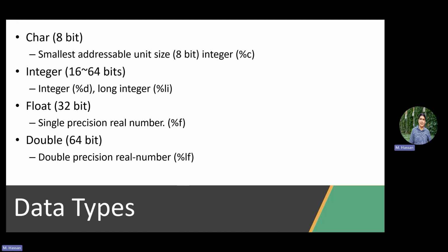Good. So why is it good to know these things? Because in the C standard, the width of an integer is in fact defined by the machine width. So if you define something like int x and put in a number and execute this on an ESP32, an Arduino, or our ST device, you will have a different width, because the integer is variable based on the machine.